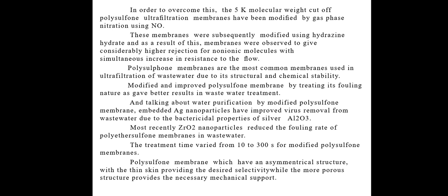Polysulfone membranes are the most common membranes used in ultrafiltration of wastewater due to their structural and chemical stability. Modified and improved polysulfone membrane by treating its fouling nature has given better results in wastewater treatment.